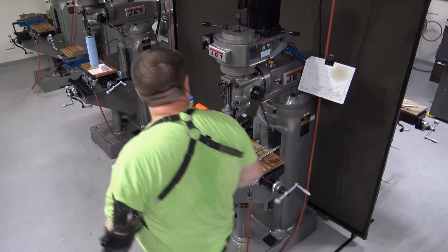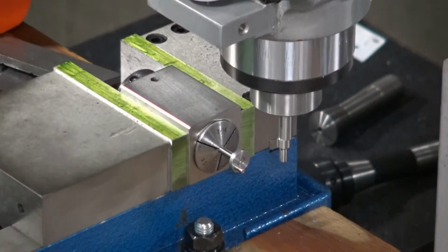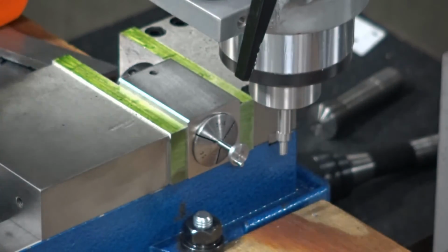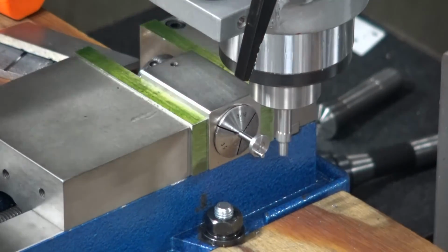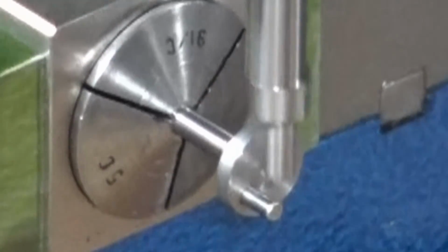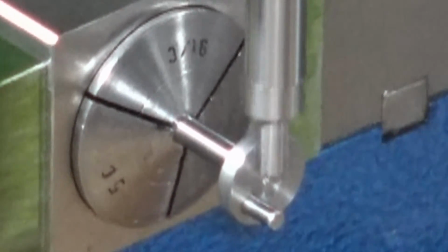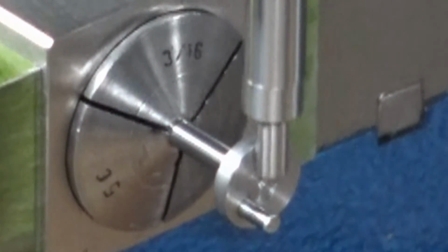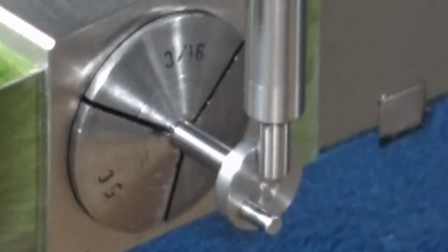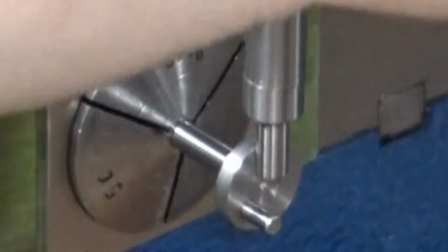My cover back on. So now I'm going to position my edge finder down so that I can do an edge finding operation right on that front face. Forward rotation. I'm going to use this hand wheel over here, which is different than what I normally would use, just because I want to make sure you guys can see what's going on. Do an edge finding on that front face. There, kicked off. Stop the spindle.